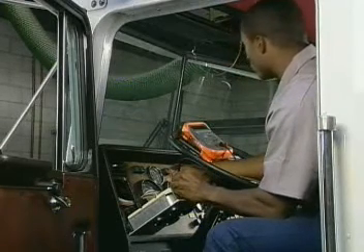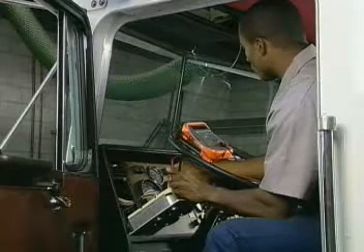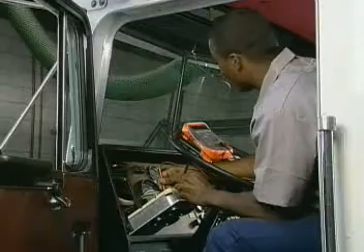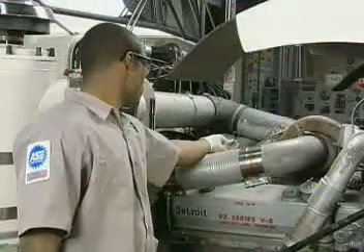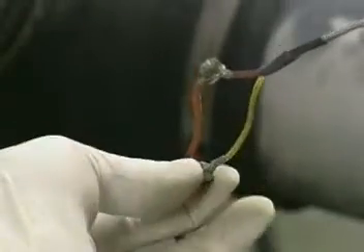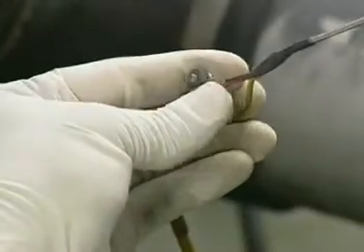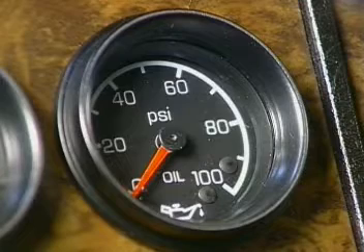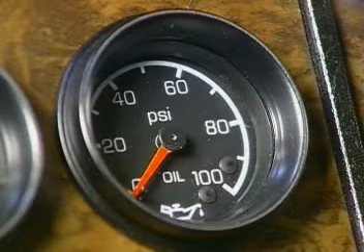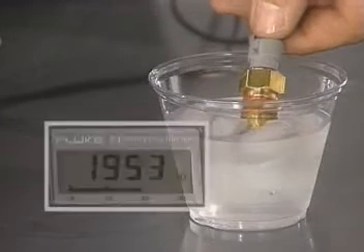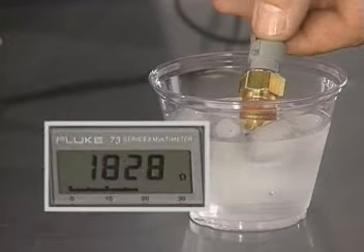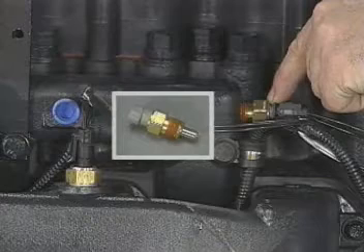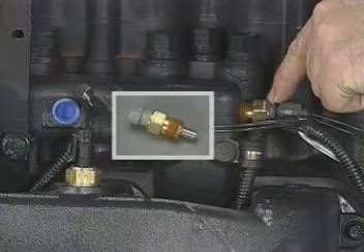High resistance in a circuit from a loose or dirty connector or a poor ground will result in a continually low signal from the gauge. Shorted sensors will result in high current flow to the gauges that can cause the gauge to burn out. A malfunctioning oil pressure gauge may be cause for an inspector to deadline a vehicle. On vehicles where the sensors are ECM inputs, the coolant temperature or oil temperature sensor signals will cause the programmed engine derate to initiate.